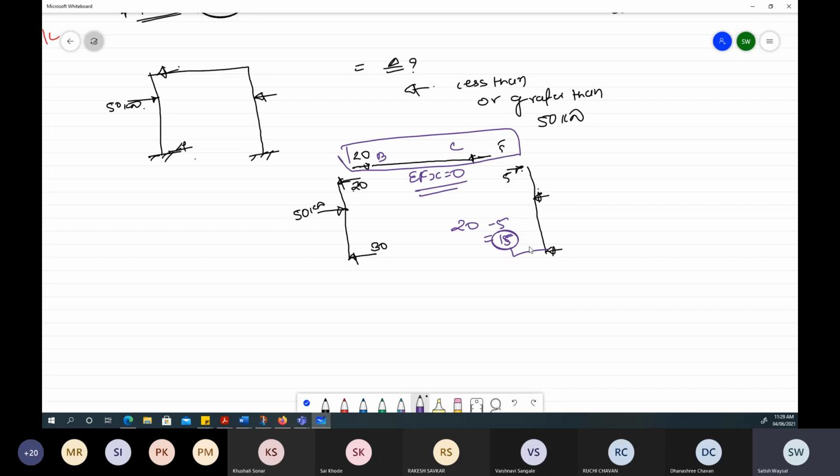So likewise, while we calculate ADL1 and ADL2, this is unbalanced moment. After determining by using the standard formula MFAB plus MFBA, this is ADL1 and ADL2. Similarly, while we have to deal with a structure which is subjected to sway, at that time you have to consider that the structure is statically determinate and find out the horizontal reactions at the columns, and the difference of these two reactions is your ADL, or that is an unequilibrium force, a force which will be causing a sway in the structure. So we have to look into that aspect for this type of structures.